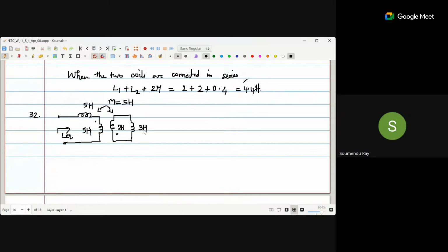No, that is not it. That depends on what your voltage is. That voltage is the inductance voltage. It can be positive on the... Fine, then you don't take it that way. You just go with the dot convention. So if I take the dot convention only, then I have to take V1 is equal to L1 di1 by dt minus M di2 by dt.